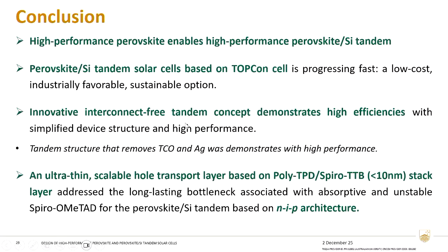I hope that's good, because it is the festive season for Christmas, but I would also emphasize that there are still a lot of challenges for the perovskite and tandem field, particularly for the scalability as well as the stability. Just to give you a few numbers, in less than 1 minute. For the perovskite silicon tandems, the highest efficiency for the small lab area, 1 square centimeter, is 34.9% efficiency.